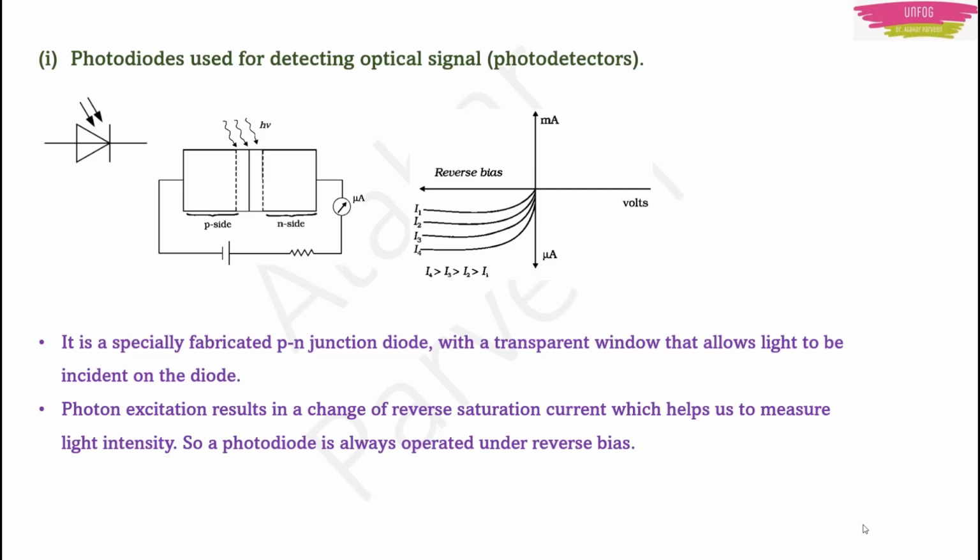So, one question can be asked like this: photodiodes operate at... The answer must be reverse bias condition. So, what is the difference between a PN junction diode and a photodiode? A photodiode, being a PN junction diode, is not operated at forward bias. Remember, a PN junction diode was operated only in forward bias, but a photodiode is operated in reverse bias. One more difference is that photodiodes are optoelectronic devices. If light falls on it, then only it will work. Okay, so this was about photodiodes.